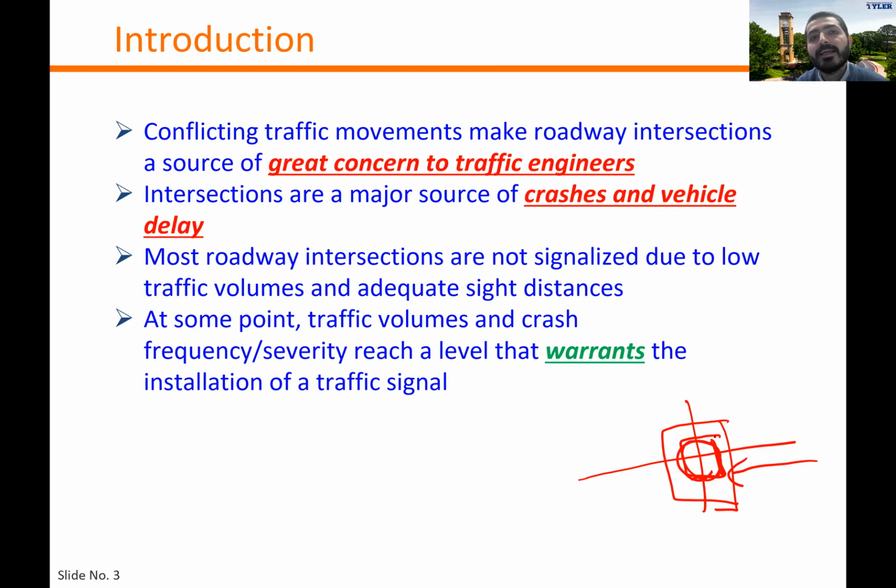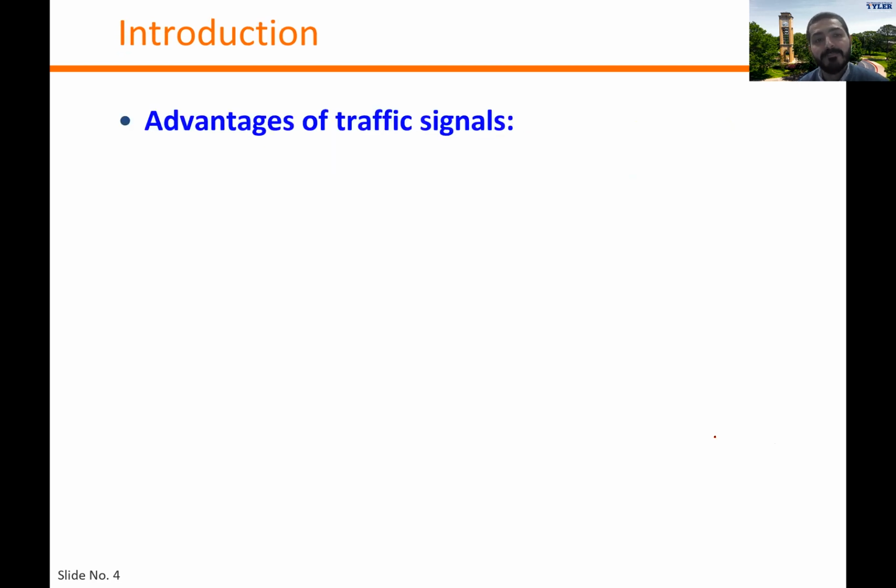At some point, at any of these unsignalized intersections, once the traffic volume or the crash frequency starts to increase, or the severity of the crashes starts to increase, that can warrant, or satisfy the need for, installing a traffic signal.